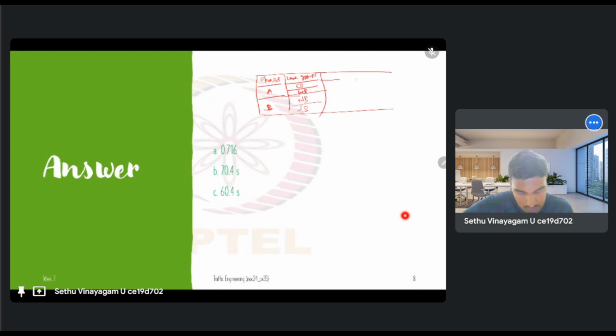And for each lane group, what do we have? We have QI, which is the through-equivalent lane volume per lane. We have no turning movements here, so we already have the equivalent lane volume. For the eastbound movement it was 340, for the westbound movement 420, for the northbound 550, and for the southbound 450. This is the incoming flow volume.